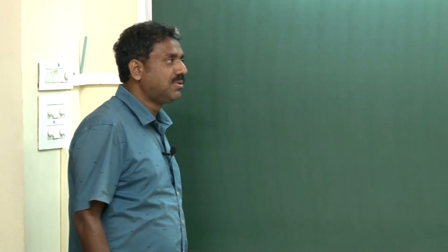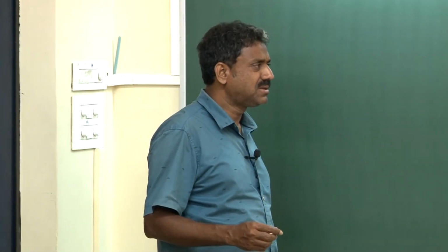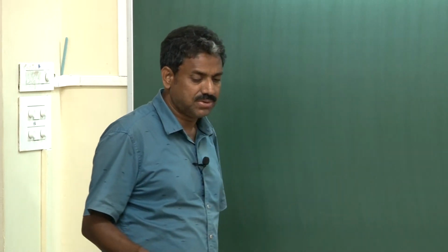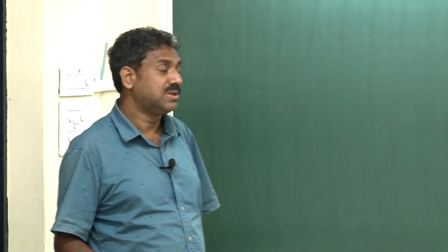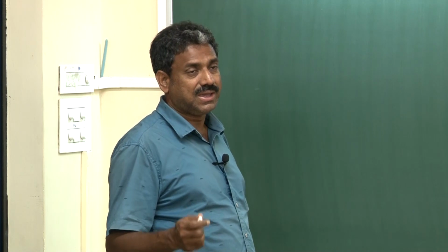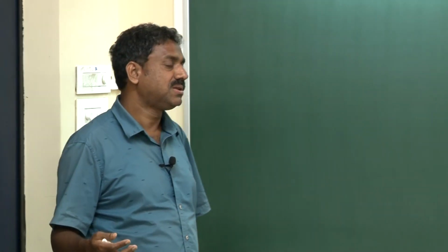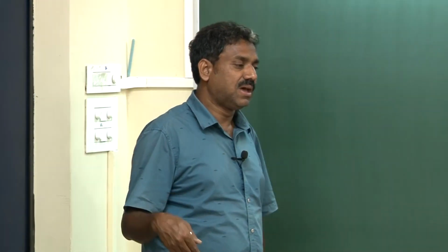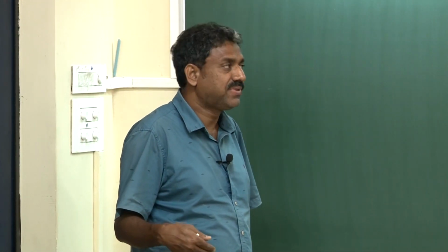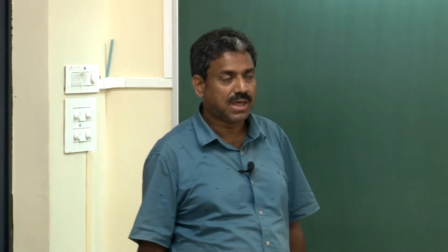For that we have adapted a similar approach as in Donnell's equation, but we have kept the out of plane equilibrium equation and the in plane equilibrium equation separate, and of course there will be coupling.